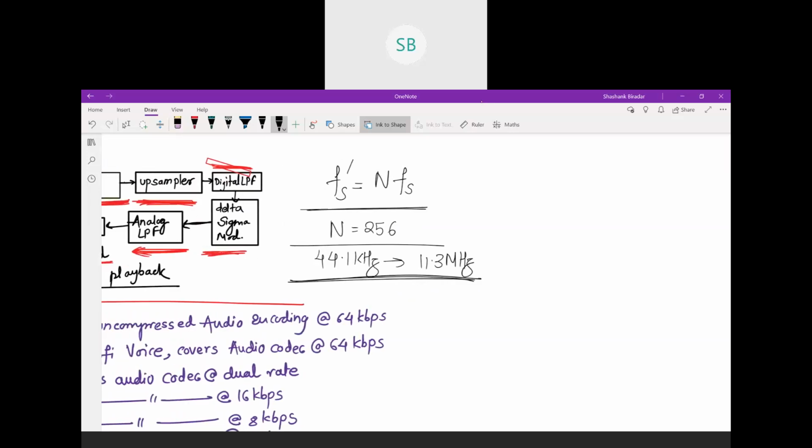Okay, right. So this increases the sample rate and brings the adjacent samples very close to each other, and the amplitude difference between adjacent samples will be very, very small. Now this allows us to use the delta sigma modulator as a 1 bit DAC. Again, upsampling and all those things we can do as long as we have the digital data. But in the end we have to listen to the sound, which is analog, so we need to convert that into the analog domain. For that purpose we are employing the delta sigma modulator.